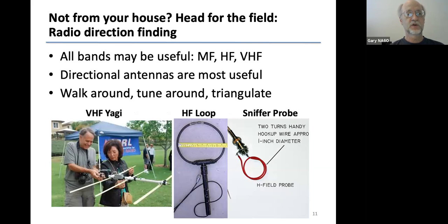That's the good old AM broadcast band, all through the HF bands, on up into VHF. Now, if you spend all your time on the repeaters, FM, VHF, things like that, you're a little more immune to a lot of interference. FM, for one thing, is fairly resistant, because most of this noise tends to be amplitude in nature. But once in a while, you find noise sources that get all the way up into even 430 megahertz and so forth. So not everybody gets away free on this.